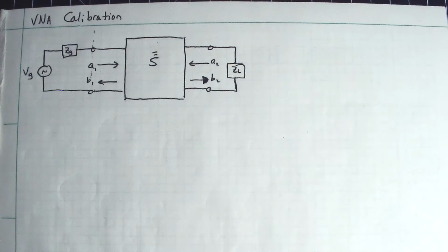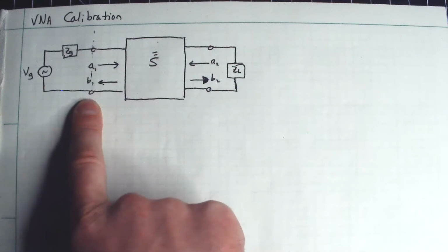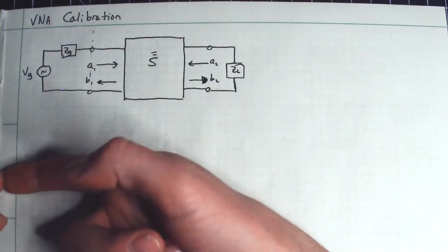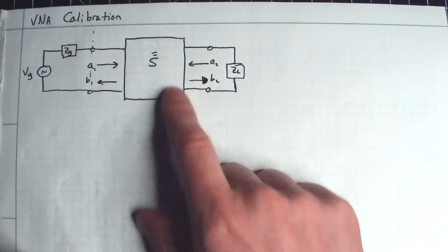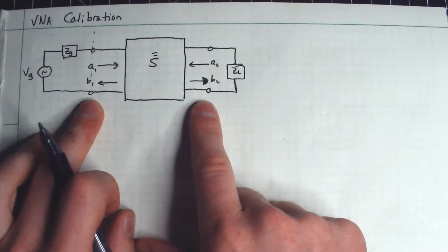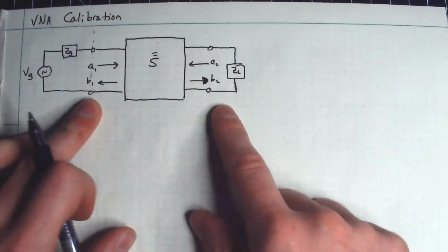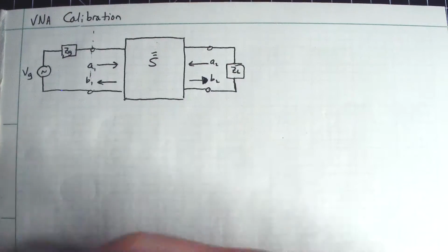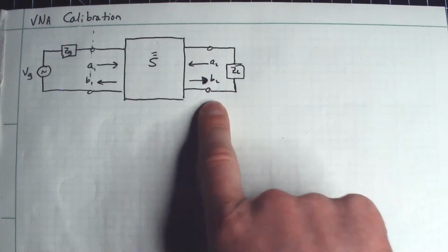But throughout this entire measurement, I only really have access to the voltage here at this port. More particularly, I could have control over the excitation signal here, and I might use some kind of coupler to get the reverse propagating signal, but I don't know anything about what's happening in this network between here and here. So this could be some length of cable between my signal generator and my load, or there could be a filter going on here, but I want to know what is happening over here down some chain of devices before I get a true reflection coefficient.